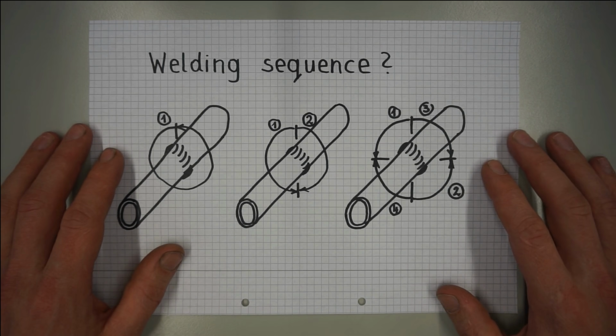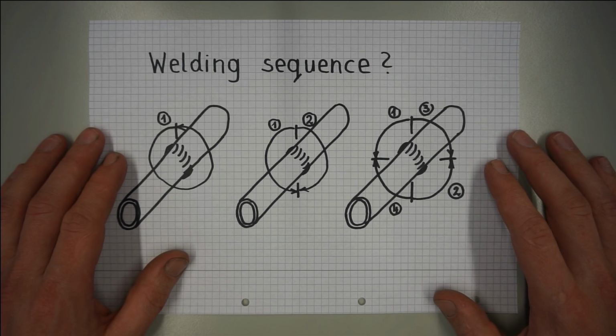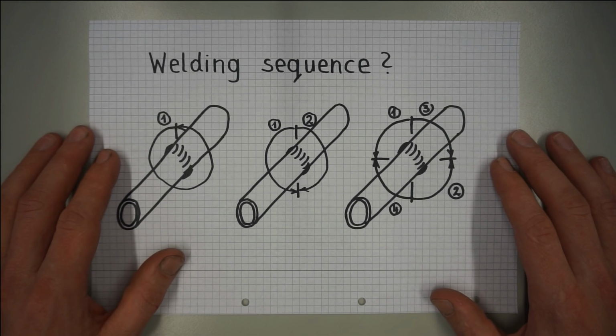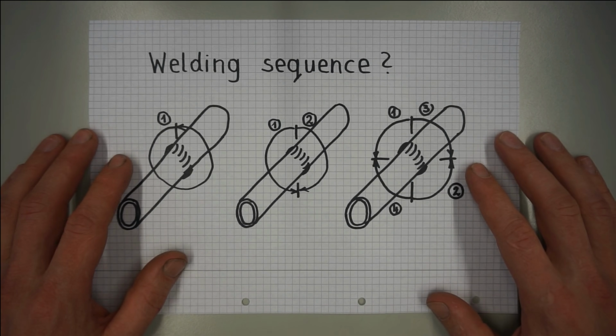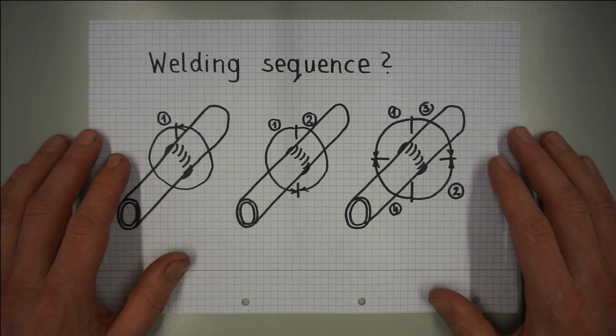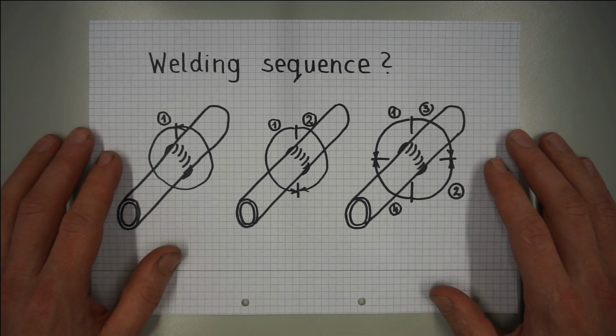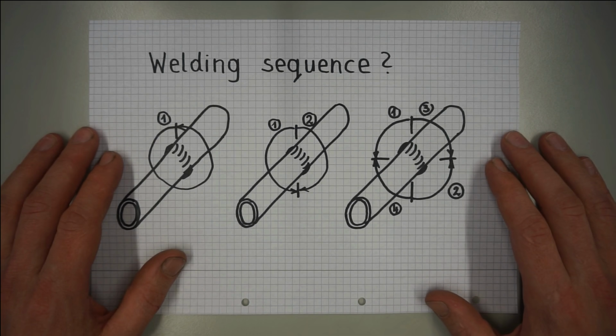Furthermore, at the same time, heat conductivity of the workpiece rises because it gets more and more connected by the welds, which may satisfy strategy number 3 by reducing heated spot size. So, you see, the whole distortional problem can very quickly become very complicated, which might be the reason why so few guidelines are available to help finding a good welding sequence.